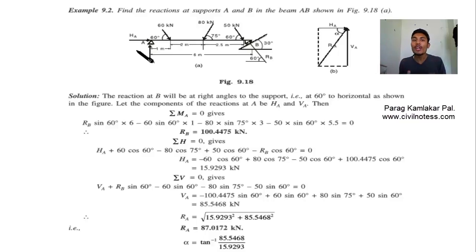Why have I told you that you have to resolve all the inclined forces? If the force acts along the axis, there is no need to resolve. But if the force is acting inclined, then you have to resolve. Why? Because the moment formula depends on the force perpendicular to the distance. So you have to formalize the moment condition and go through all these things.